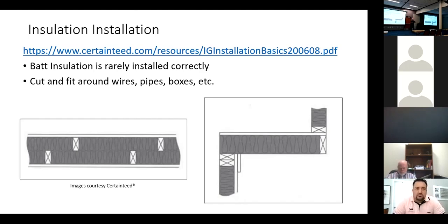You build with those, your air leakage is your doors, your fenestration, and your ceiling. That's it. You build with those, and then they do the lids, and then they come up and they spray closed cell all over the lids. You are really, really tight. You better ventilate it. I kind of went off track, but I think it's good stuff.